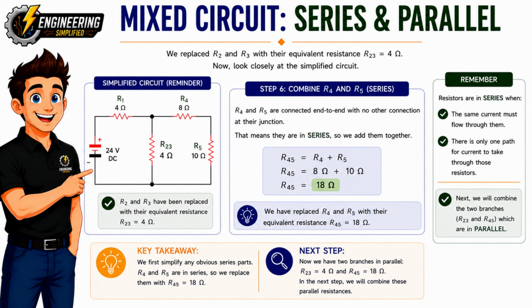Now look carefully at the simplified circuit. Notice that R4 and R5 are connected end to end, with no junction or branching point between them. That means the same current must flow through both resistors. Whenever that happens, the resistors are connected in series. And for series resistors, the calculation is simple. We just add their resistance values together. So, R45 equals R4 plus R5. That's 8 ohms plus 10 ohms, which gives us 18 ohms.